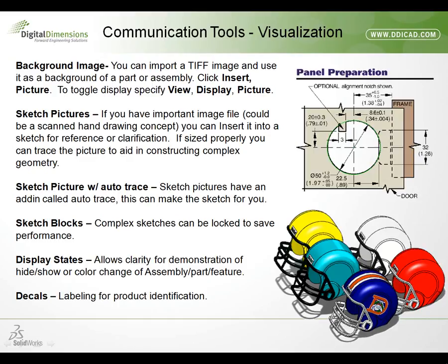So again, sketch blocks help either fairly complex sketches with a bunch of dimensions and relations that make SOLIDWORKS calculate with every rebuild, or on the opposite end of the spectrum you have a bunch of underdefined sketch entities, be they from AutoTrace or AutoCAD drawing files that have no real dimensions at all, but yet are dimensionally accurate. Sketch blocks will lock them down as a unit.